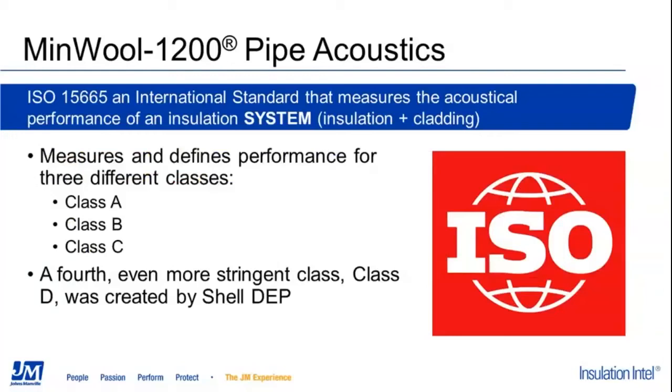And it is important to note that the way this standard and the test methods that it outlines are defined, it is a standard relevant to the entire acoustic system, not just the insulation material itself. So if the system consists of a combination of an acoustic insulation material, mass-loaded vinyl, and jacketing of some kind, either metallic or non-metallic jacketing, the entire system, as configured, must be tested.